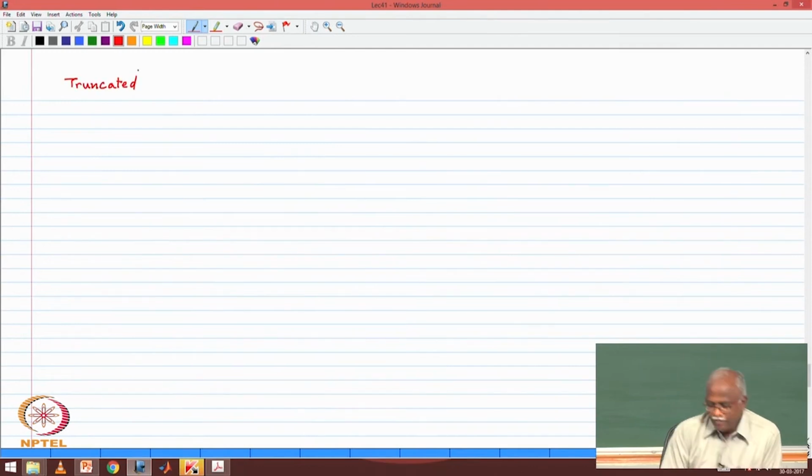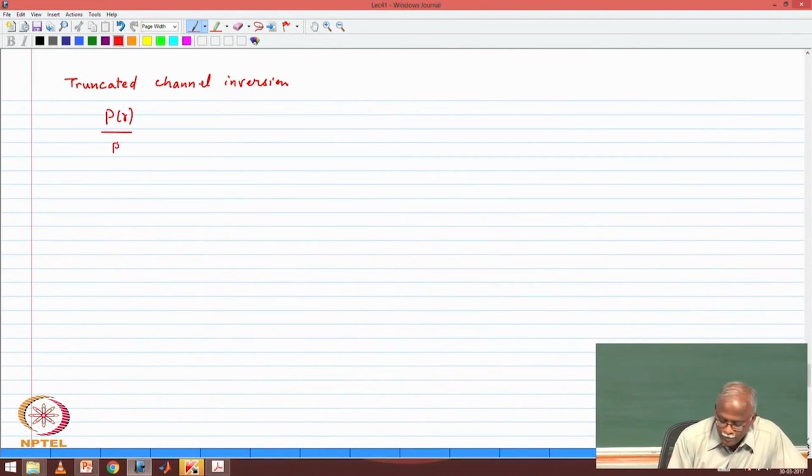So I'm not going to invert all the channels. I'm going to say, okay, when it's very bad, ignore. Only the reasonable channels I want to do channel inversion. So that's called truncated channel inversion, because you do not want to mess with the very bad channel conditions. So basically what we are saying is P of gamma divided by P bar is going to be channel inversion, sigma by gamma, only when gamma is greater than or equal to some threshold gamma naught, and is equal to 0 otherwise. Okay, so no power allocation under bad channel conditions.